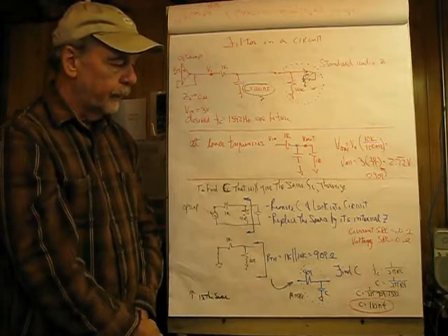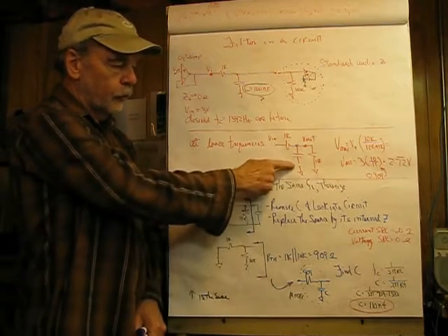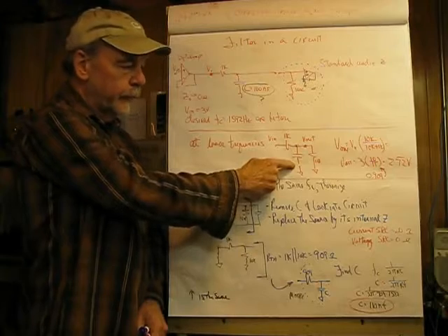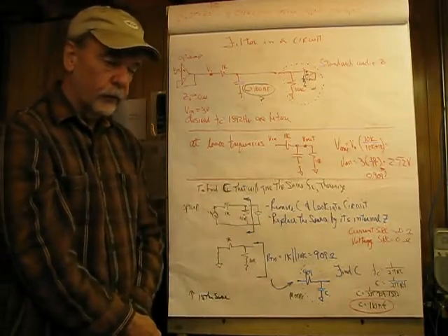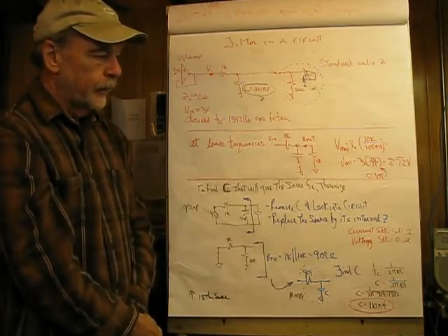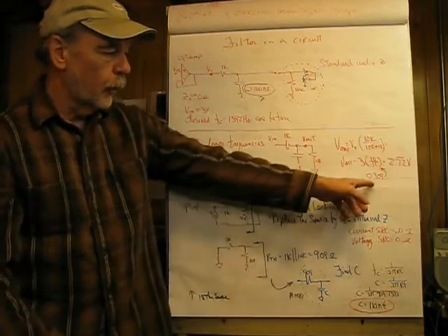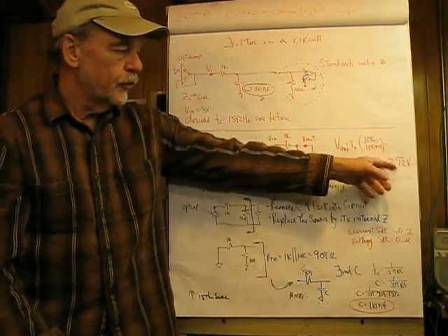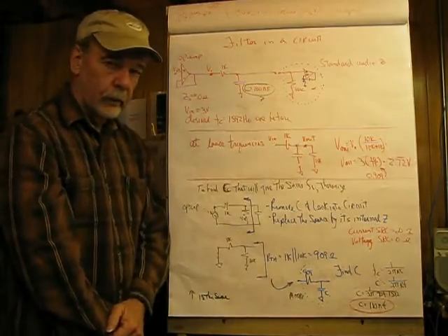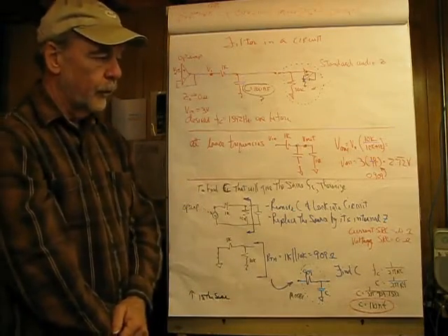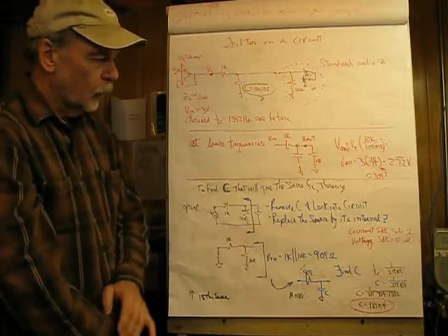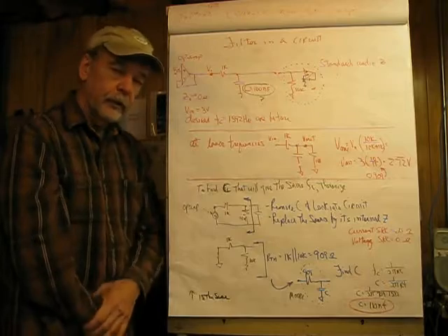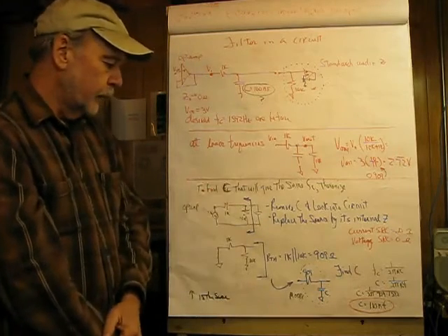Okay, what we know about that is at low frequencies the capacitor looks like an open, so I've left this open, and now I'm simply dividing with a 1K and 10K in a voltage divider, and I see that that ratio becomes 0.909, which means the output voltage at really low frequencies is going to be 2.72 volts. So I'm not going to have my 3 volts output as I did before when I was unloaded.